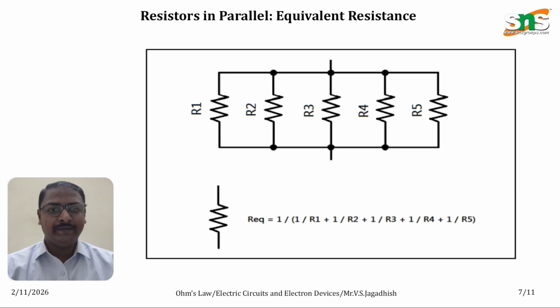And finally, we have discussed how resistors connected in parallel have to be converted into a single equivalent resistor, and the formulas of both series and parallel connection for finding out the equivalent resistors. So I hope this session gave you a small idea of what is Ohm's law and how the resistor is represented in the circuit, and converting series and parallel resistors to equivalent of its resistance.